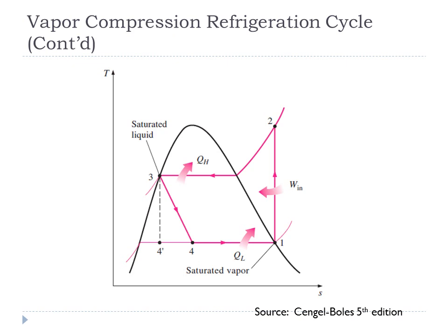At point 3 we see the point is lying on saturated liquid line, so the refrigerant has become liquid refrigerant at point 3, and at point 3 it enters into the expansion valve, where it is expanded using throttling process, and 3 to 4 is the expansion process. At point 4 we can see the temperature is very low and pressure is also very low.